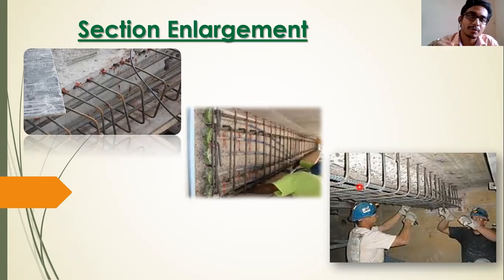So why is undercut important? Because undercut means going somewhat deep, behind the reinforcement also. You can see here very nicely that the shadow of the bar is coming. So there is a gap in between the bar and the concrete. So undercut is very, very important.